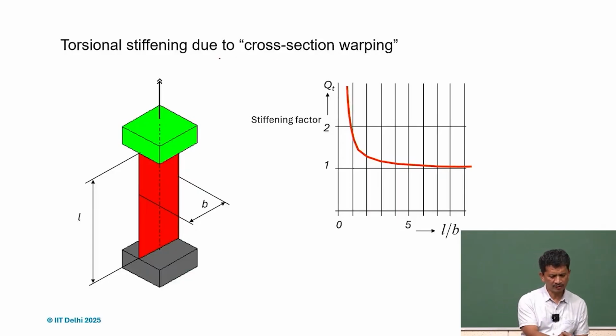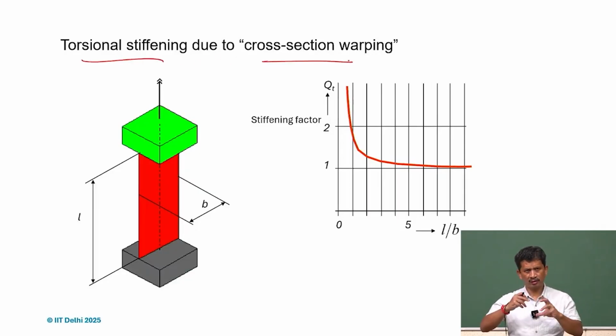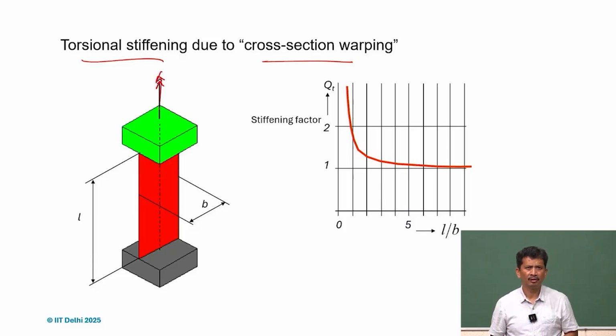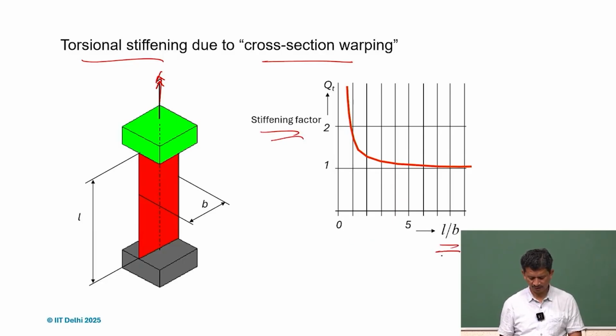Moving on, if we just use the thin strip sheet flexures, as we are calling them, we know that they are again torsionally compliant members, so we twist it and we can get this deformation. What happens as we twist is that there will be a stiffening factor. So as L by B is large, that means we can twist it easily. But as it gets shorter, the stiffening factor will be very high.